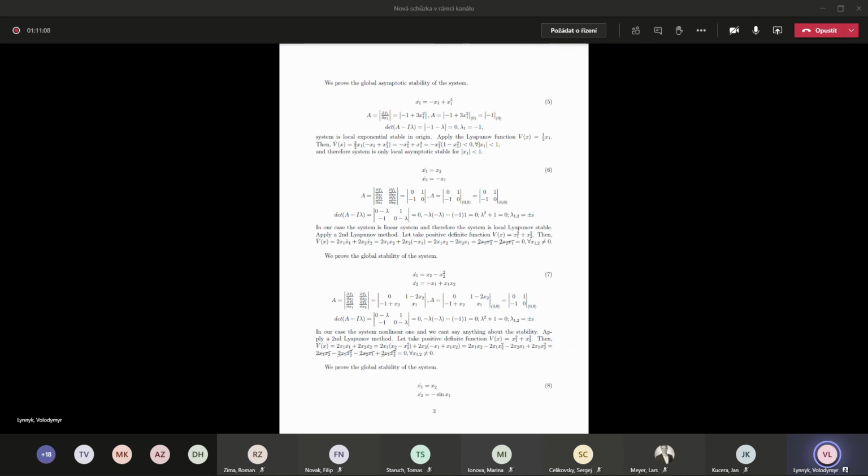When we start at some point we can go to one of these stable points, and if we want to analyze this system by the first Lyapunov method, we only know that if we apply the indirect Lyapunov method to the nonlinear system and find that lambda 1, 2, for example, equal plus minus j, then we need to apply the direct Lyapunov method.